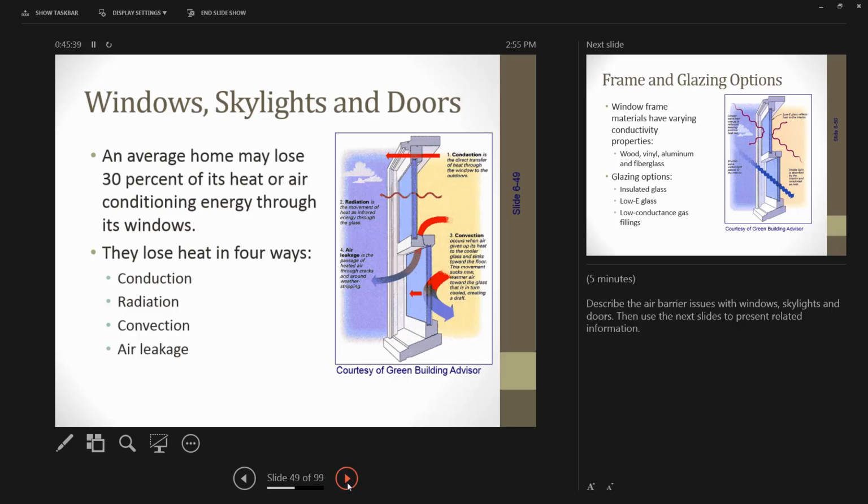It takes significant detailing in design. And so backing off of the concept of trying to get walls completely airtight is making sure that we're accounting for moisture that can get in the wall and allowing it to dry. We'll talk about that more in just a minute.